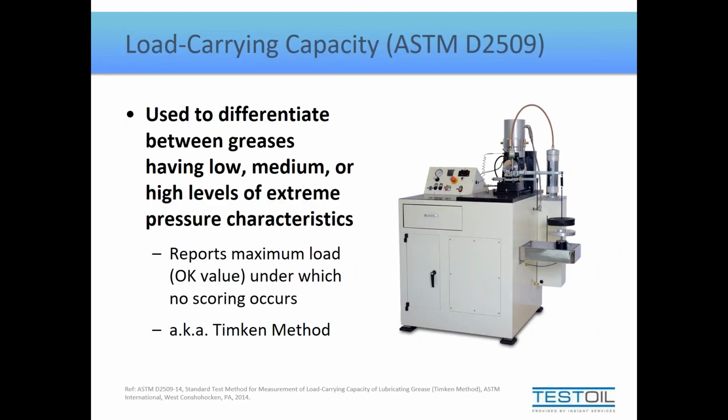And most oils do not perform well in this particular test rig, or even the condensed version of this test rig, unless they have been treated with an EP additive. So just kind of food for thought, if you ever see something that's similar to this one, looks like basically everything sitting on top of the bench, not the entire bench with it, make sure you know this test is meant for defining or characterizing EP characteristics and not for any other property of a lubricant.